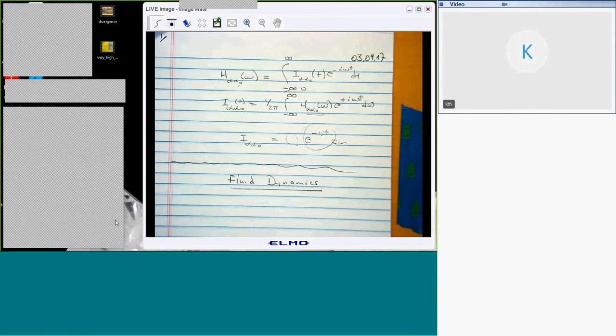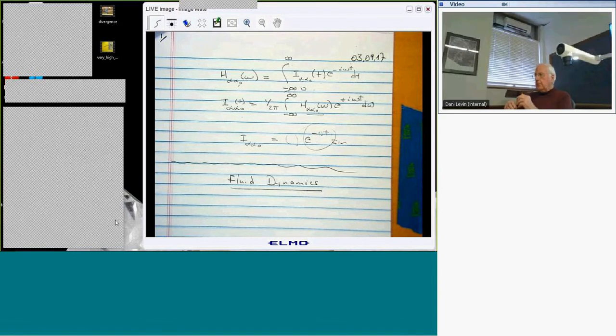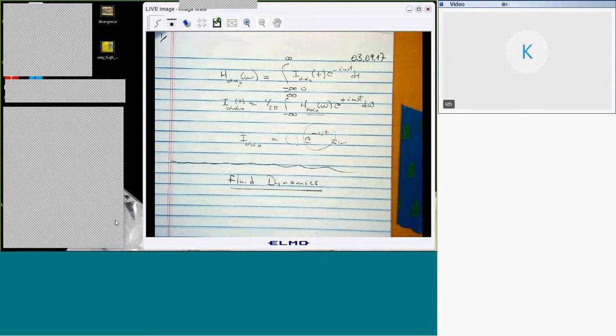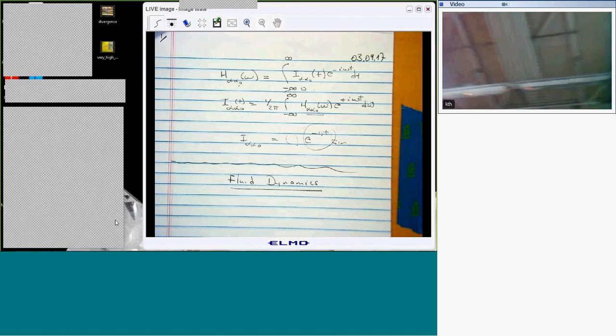You have density of the fluid, and you have the two components of fluid velocity, plus you have pressure, even in inviscid aerodynamics. So you have 5 unknowns and 4 equations, and so you've got to do something about that. So you appeal to thermodynamics, which gives you a relationship in isentropic processes between pressure and density. That gives 5 unknowns, 5 scalar equations, and you're in business.